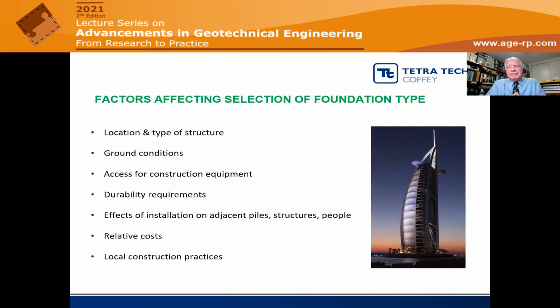Now, there are a number of factors that influence our selection of foundation type. Clearly, the location and type of structure, the ground conditions, the access for construction equipment, that is often very important because if we're in a congested urban area, there may be foundation options that we cannot use because construction equipment can't get there. Then we have the requirements of durability.